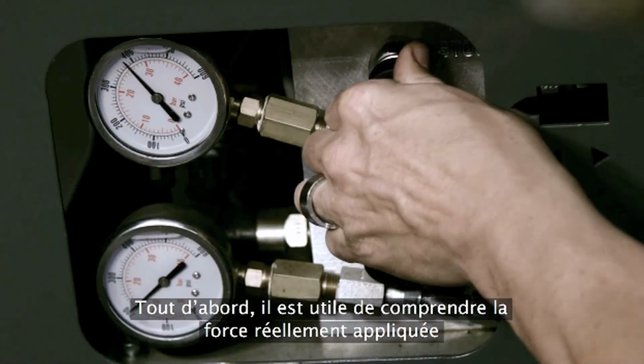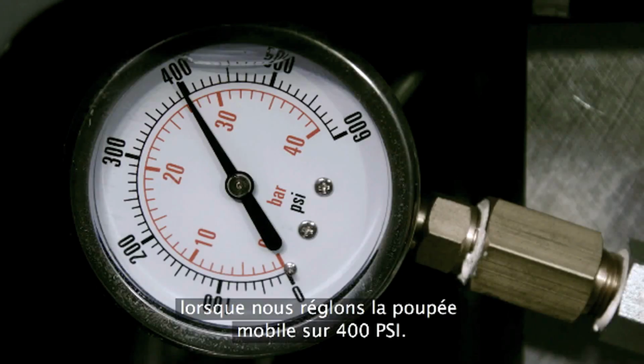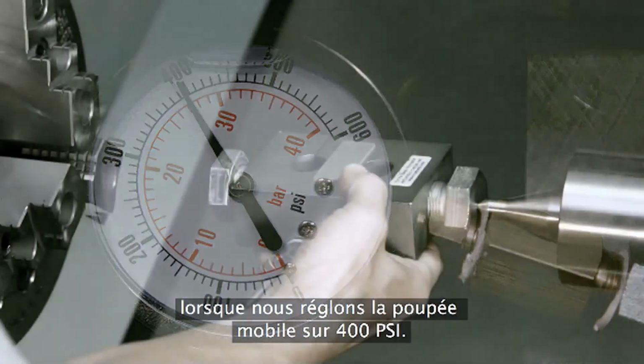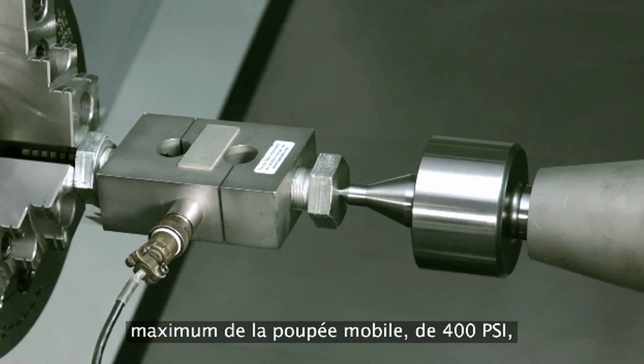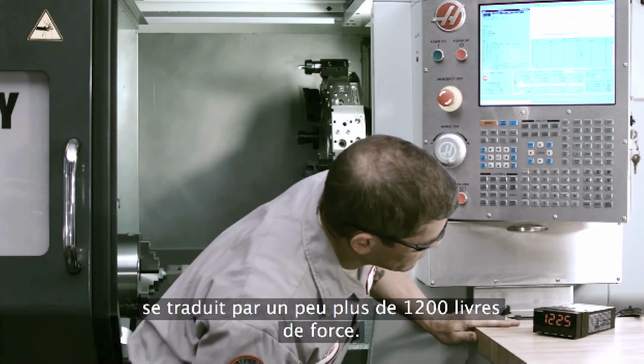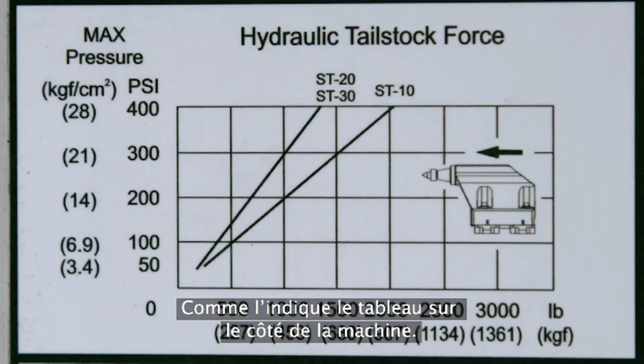First, it's helpful to figure out how much force is actually being applied when we set the tailstock to 400 psi. Using this load cell, we can see that our max tailstock pressure at 400 psi translates to a little over 1,200 pounds of force, the same as what the chart on the side of the machine says.